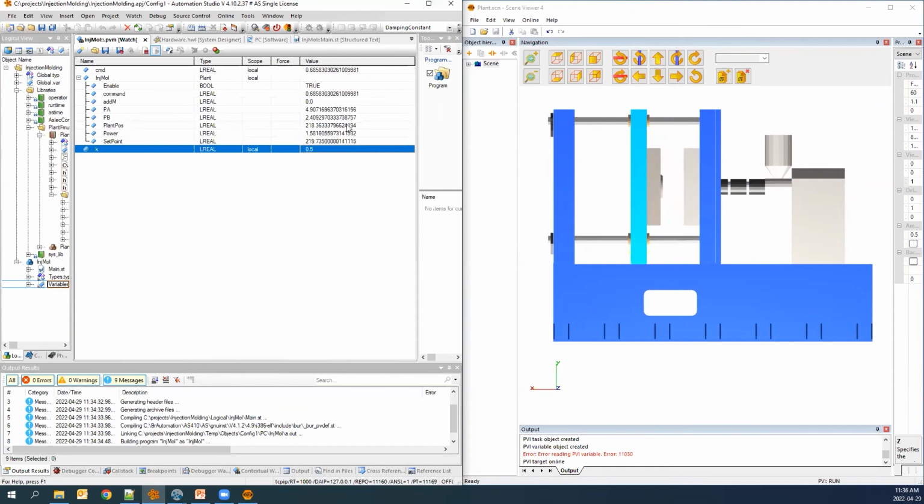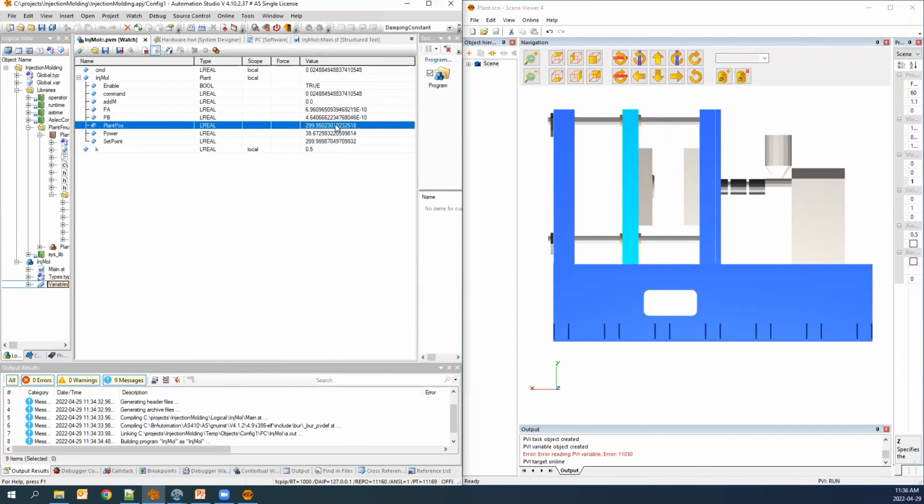Of course, we could see this by looking at the platen position. We'll see that in this case, it actually goes negative, which it didn't before. That negative is indicating it would be slamming, which, I mean, these injection molding machines are quite large. And if you slam this platen into the stationary piece, it's quite a loud bang. So this is kind of the idea, kind of the advantage.